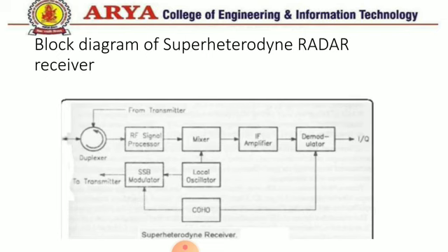So this conversion loss plays an important role in the operation of the mixer. The mixer basically uses a silicon contact diode because of its non-linear characteristics. The output of the mixer is given to the intermediate frequency amplifier.